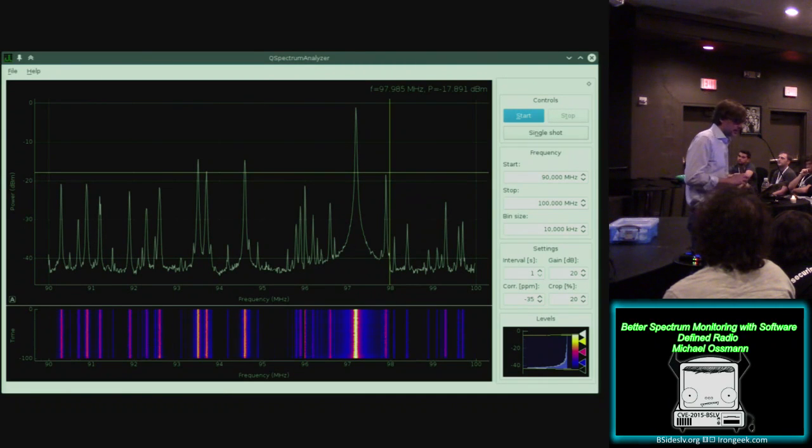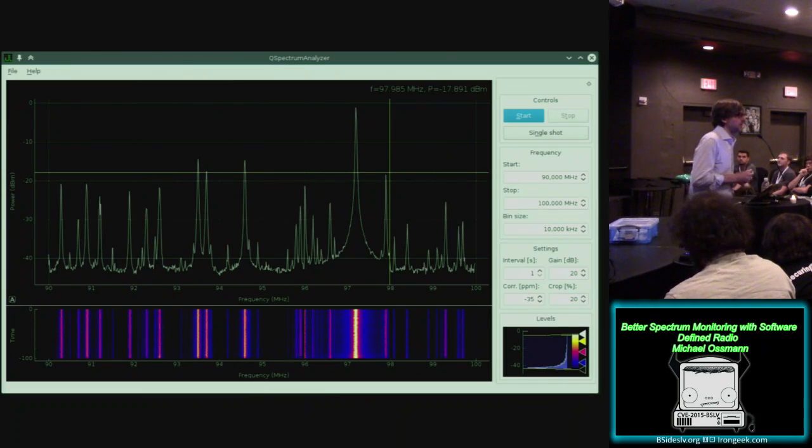And again, it's the idea of taking these low-cost hardware platforms that we have and trying to build new software for them that takes advantage of their capabilities and lets people take measurements in ways they hadn't thought of, using tools other than high-end RF test equipment like spectrum analyzers. And you can actually use an SDR platform as a spectrum analyzer.